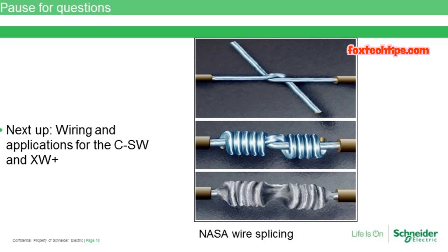When it comes to a retrofit for AC coupling, or just even if there's a good reason, like we've discussed before, about bringing in an AC coupling solution for different reasons, the thing to note is that we don't recommend through Schneider Electric choosing to use a lithium battery bank with AC coupling. In essence, this is because it's an uncontrolled charge that's coming from the AC side. So you have the solar array coming into that grid tie inverter, and it's pushing power either onto the loads or basically backwards through the inverter onto the batteries.